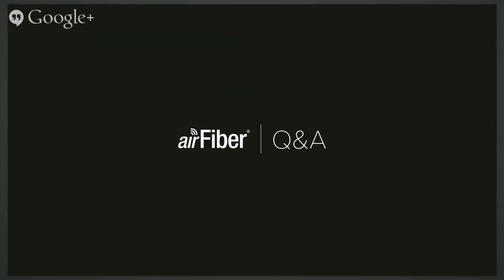All right, so the first question will be, what about performance in heavy rain or fog? What's the difference between 5 gig versus 24? Okay, there is a bit of difference there. The 24 gig spectrum is sensitive to high levels of humidity, which is rain. I don't know that fog really has much of an impact, but rain does. And so if you're in a particularly wet climate, and that's something that you find out by looking at maps that give an idea of how much rainfall you'd expect to see in a given year.